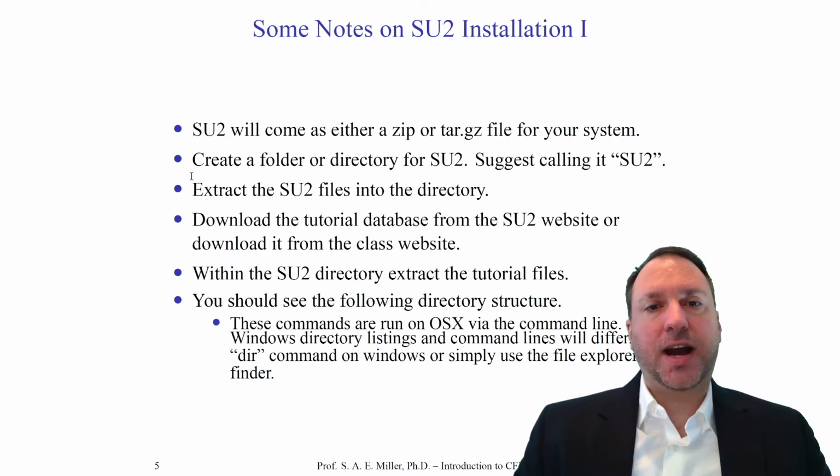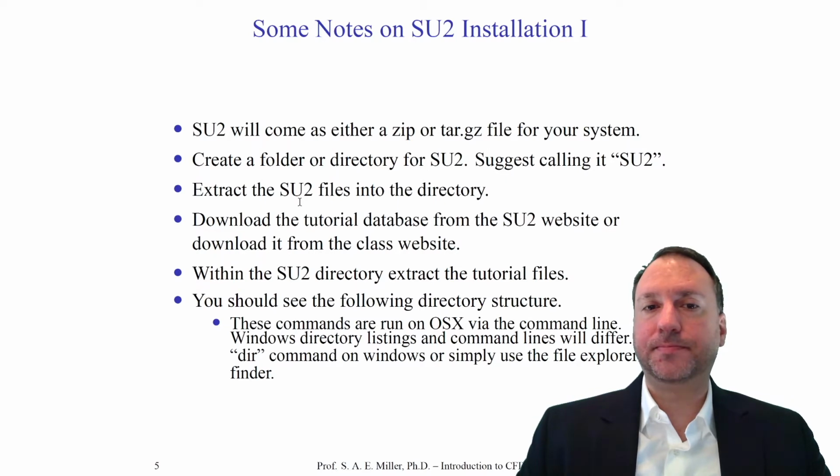Now, you'll extract your zip file or tar.gz file directly into the SU2 directory or folder you just created. This will create a whole file structure and tree with many subdirectories and appropriate files. So that's why it's appropriate not to just put it in your home directory itself.